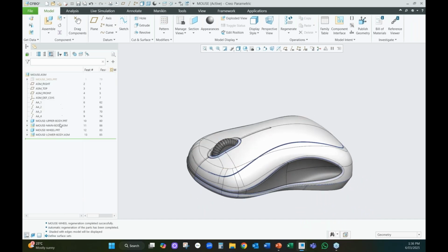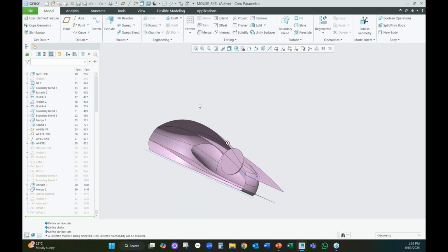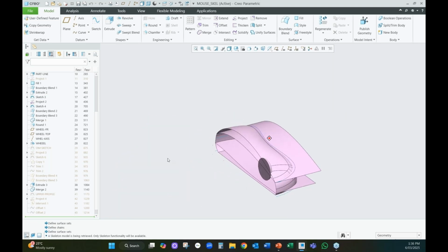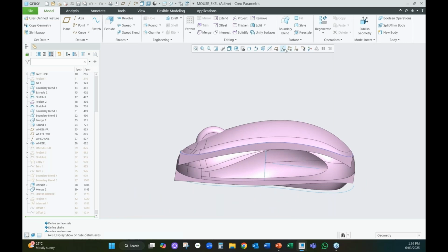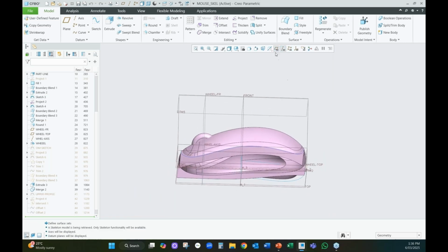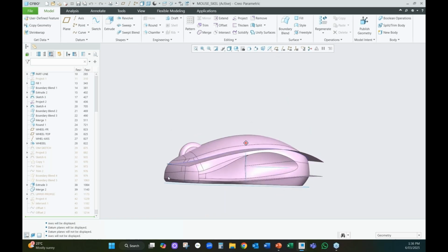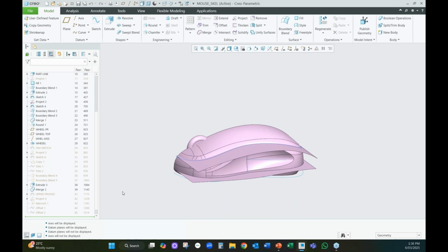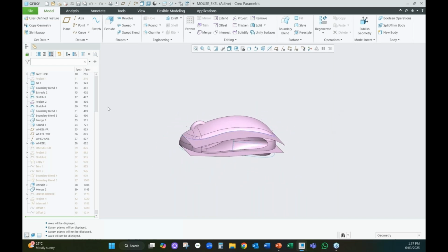So if we have a look at the architecture from the top, if we open up the skeleton, you can see, certainly as I was saying before, this one is all surfaces and curves. We've also got some axes in there. There's a wheel axis. There's some datum planes, which I use to constrain the curves. But this one set of geometries controls the entire look, shape, feel, part line interaction, and how the different subcomponents go together.